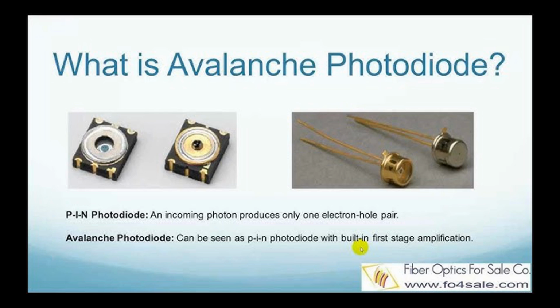Impact. Dark current introduces noise into the system, reducing the accuracy of low-light measurements. Minimization. Cooling the photodiode or using materials with lower intrinsic carrier concentrations can minimize dark current.